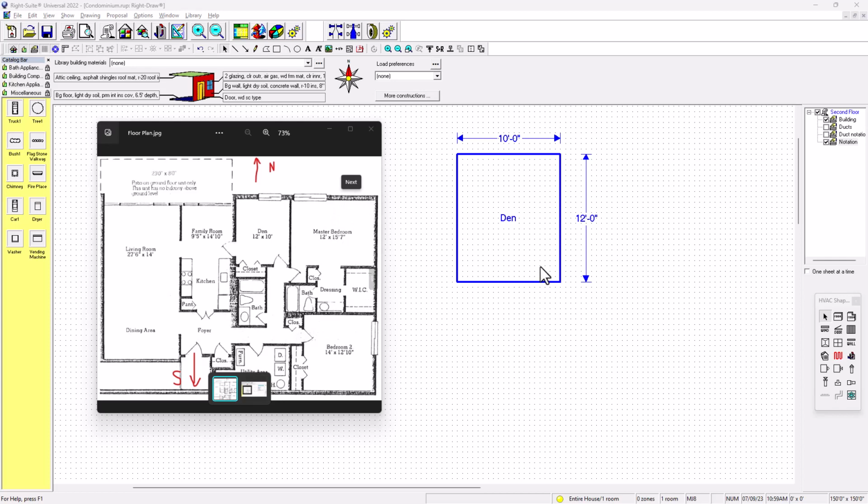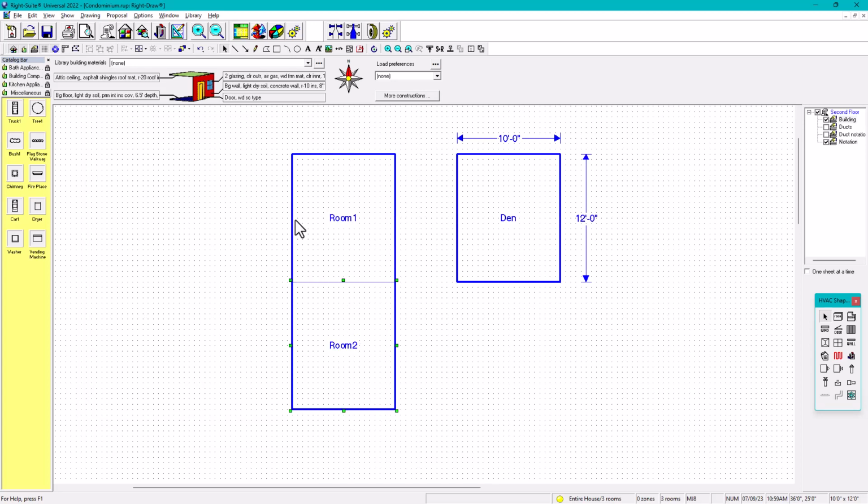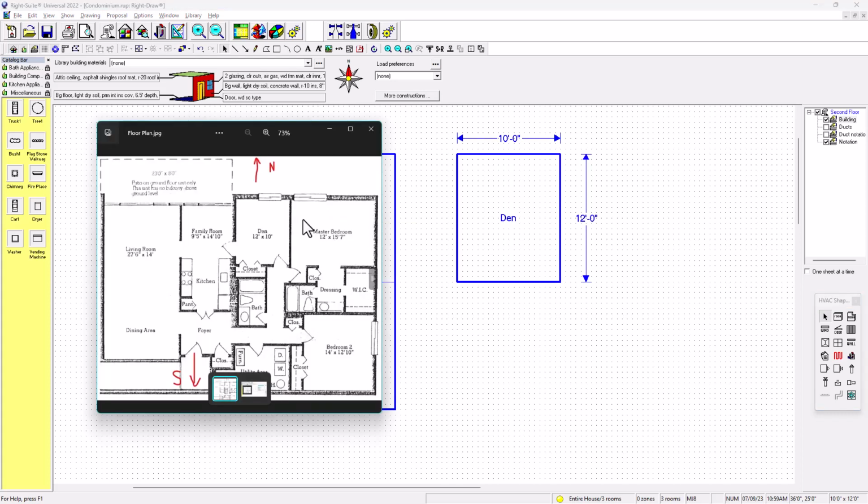So in other words, I'm going to explain the following. If you do your heat load calculation following the interior dimensions, your exterior dimension is not going to show the same value as expected. In other words, you're going to end up being short. You put the interior dimensions and then you're going to end up right here. So that's the part that we need to be careful about.